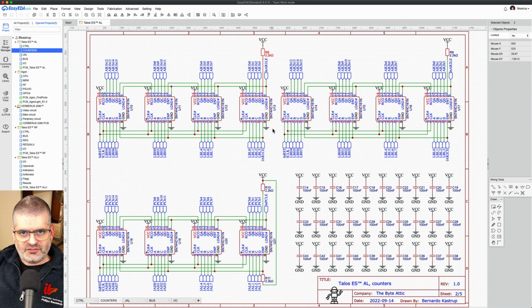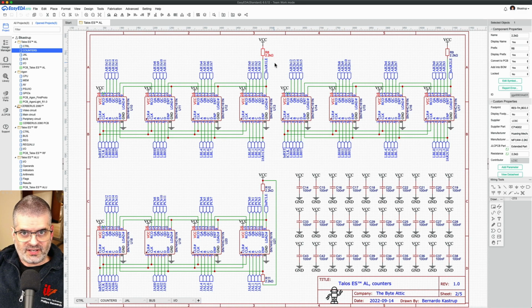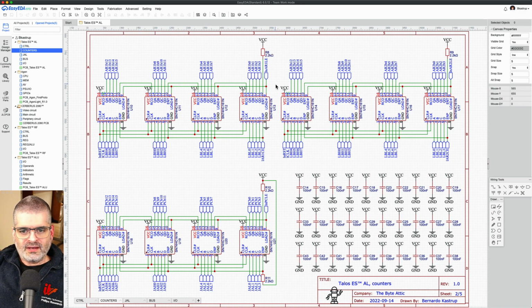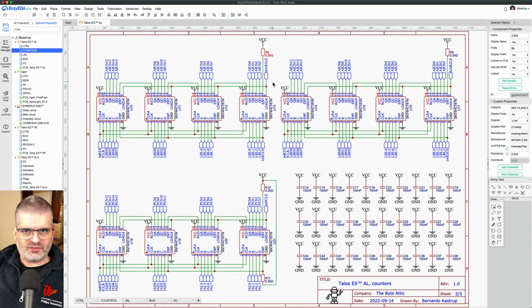For instance, the 6502 processor has a pin that is an I/O. I believe it's the out pin. You can halt the processor from the outside by pulling that pin down, but sometimes the processor puts itself in a halt state or in a wait state, so it pulls its own pin down, and then if you put 5 volts on that pin and the processor tries to pull it down, you have a short circuit. So to avoid that, you have to put a little in-series resistor like this.